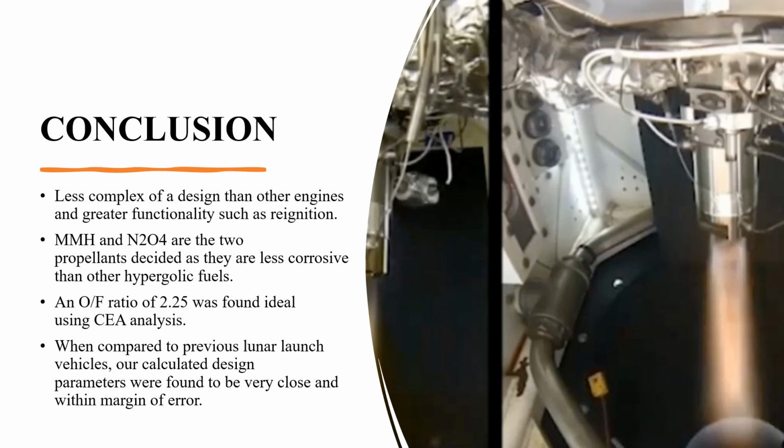Notably, the hypergolic engine produced slightly less thrust, but boasted a greater specific impulse, with a lesser overall mass and a different nozzle configuration. This ultimately meant that our engine could meet the performance standards needed for its mission. While still theoretical, our newly designed engine is at the very least demonstrating that a lunar ascent vehicle could realistically be propelled by a hypergolic engine into orbit based upon past mission parameters. Additionally, implementing the new engine would allow for the removal of additional engine components, like an ignition source.